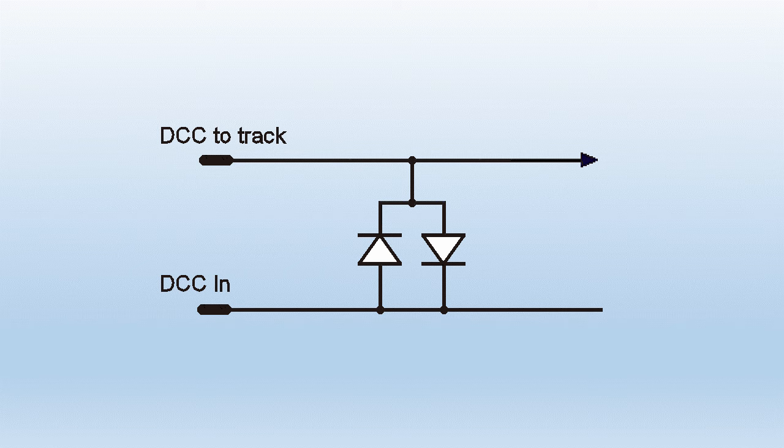However, if a loco is in a track section, current will flow and the voltage pulses will be developed across the diodes. And that's true whether the loco is moving or stationary, because even the small amount of current being drawn by the DCC decoder inside the loco is sufficient to develop these pulses across the diodes. And the rest of the kit's circuitry detects those pulses and takes appropriate action by changing its output.